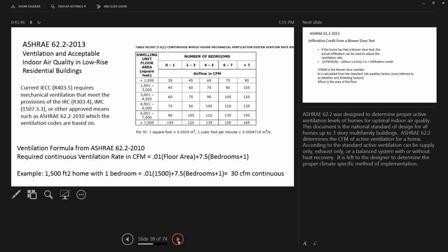And so ventilation becomes a big issue. It's a big issue both for occupant safety and health, so that the air they're breathing doesn't have a high level of toxicity and volatile organic compounds in it. It's also a big issue for the moisture migration and the moisture drive that I was talking about.